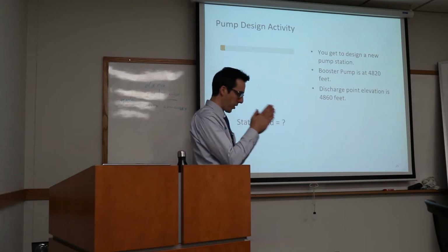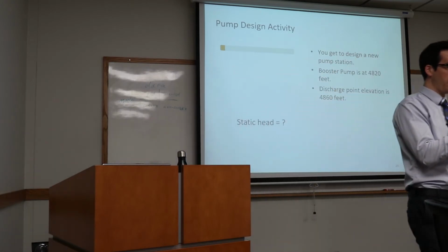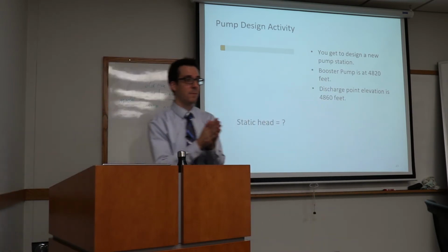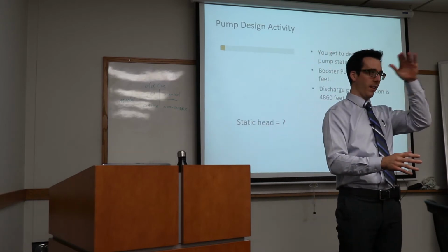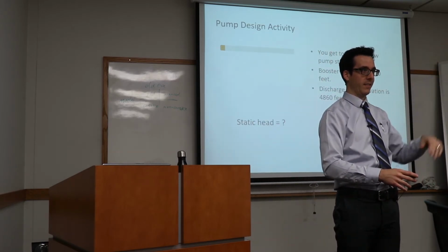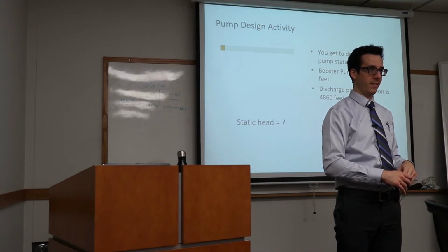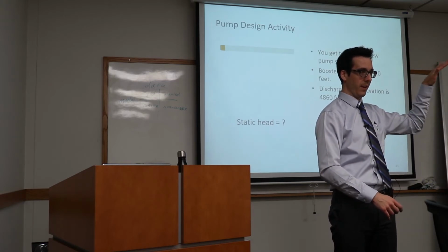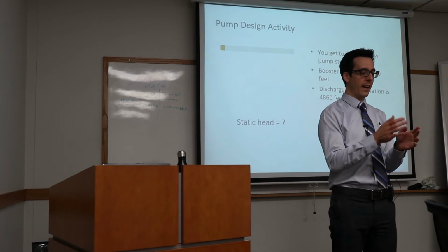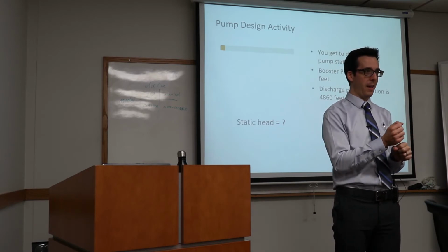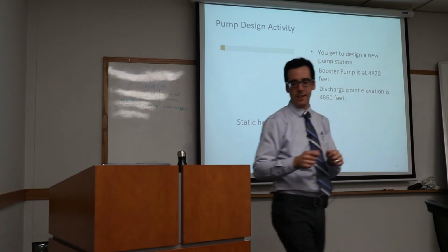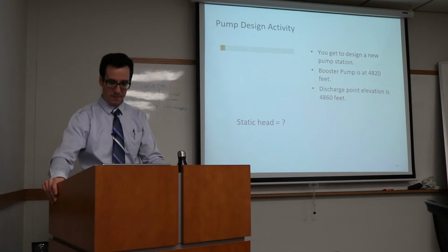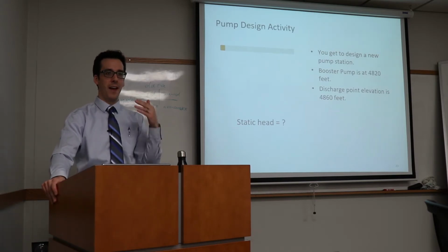So on your curve, you're going to first draw the system curve. So is the system curve going to look like this or like this? That's going to curve up. Yeah, so the pump curve goes this way, the system curve goes up to the right. Okay, so at zero flow, what is your system head? 40. Okay, so mark that on your graph. Use a circle, and we'll put in some other points momentarily. So at zero flow, we have 40 feet of head.